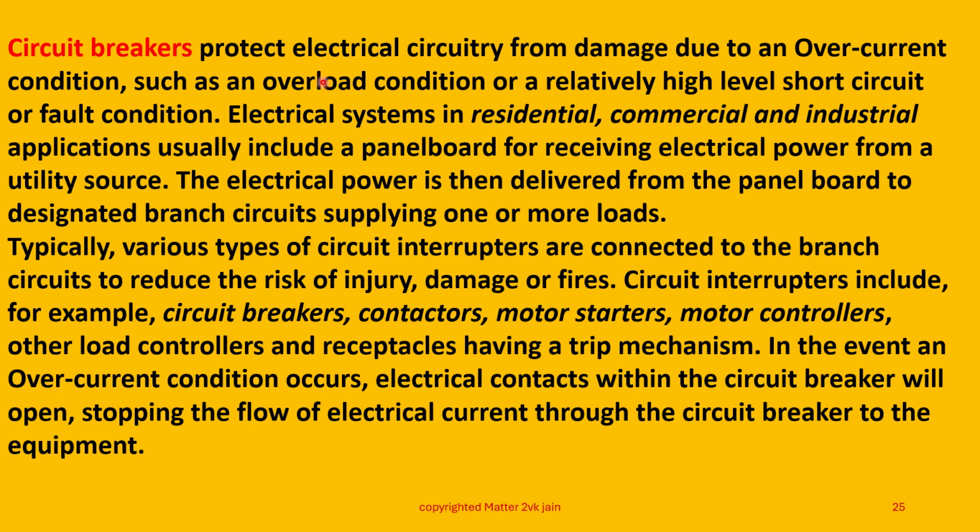As I told you, the overload is normally taken as 125% of the rated capacity, and a short circuit fault condition takes 7 times the normal full load current.